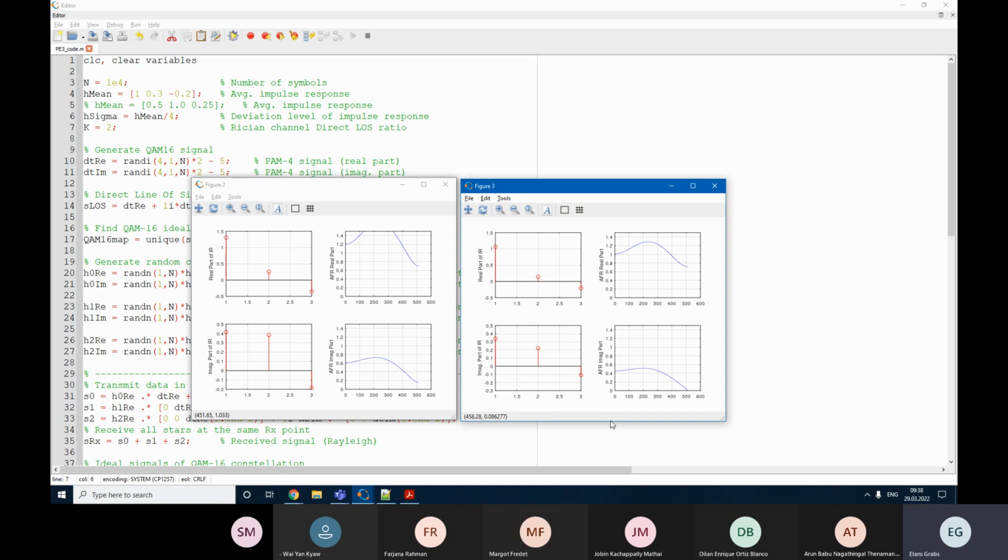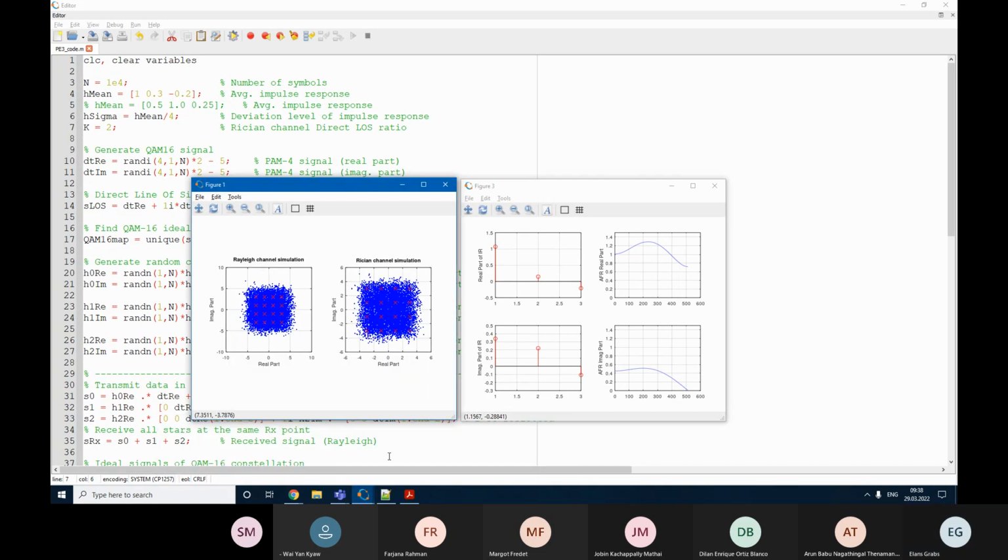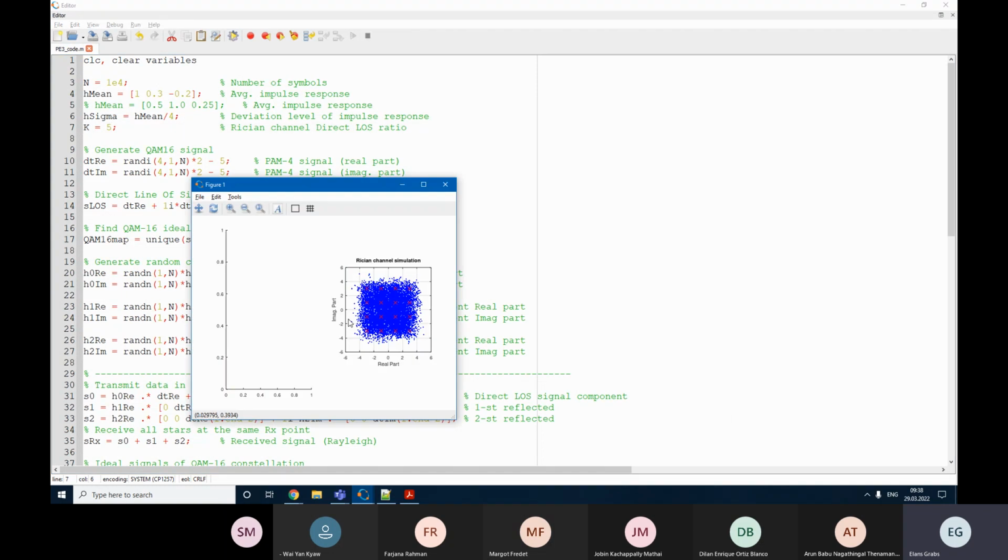But again, in fact, quite interesting scenario here. As you can see, the first value, because of the randomness, has decreased up to 0.4, which is comparable with the second value, yes? But for the right-hand channel, there still is some small difference here. Let's see how does constellation look like. I believe they should be quite bad. But no, for a right-hand channel, we can see some blank spots here, and basically not really much improvement from the Rayleigh channel, but with the ratio of 5, this will become better, yes.